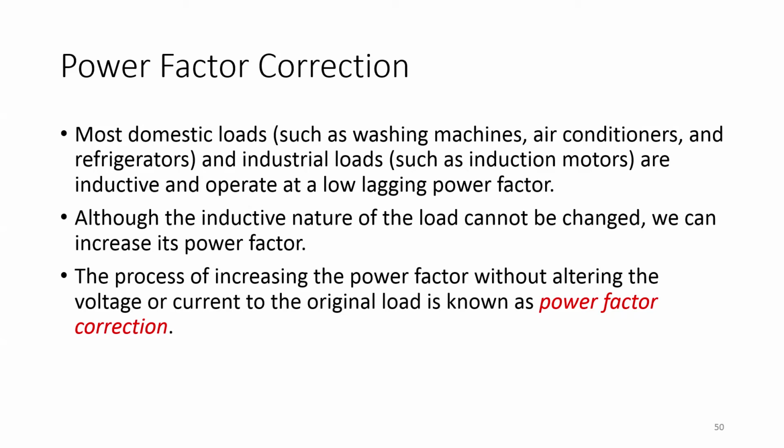This lagging power factor demands an extra reactive power from the grid, and the nature of the electric power appliances cannot be changed. They will remain as they are because there need to be motor windings and coils in order to get the motor action done. However, we can improve the power factor of our appliances, and in this lecture we are going to see how this will happen.